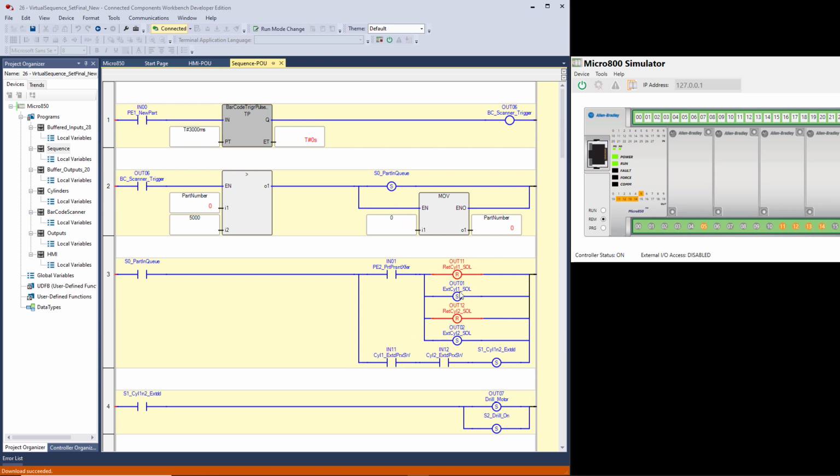So there's a valve to retract and a valve to extend, or rather I should say there's a solenoid. They're double solenoid valves. One solenoid shifts the spool in one direction and causes the cylinder to extend, and then if you turn that off, it's spring return to center. It holds position. If you energize the other solenoid, then it causes the cylinder to go to the opposite position. So that means you have an output to extend and an output to retract.